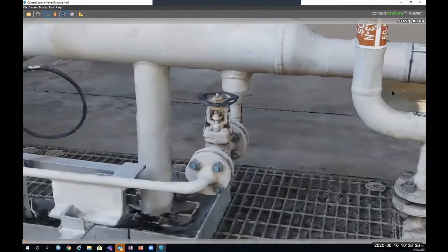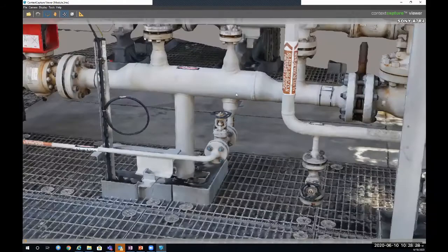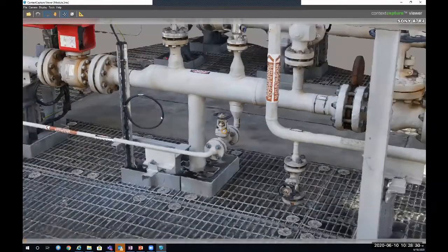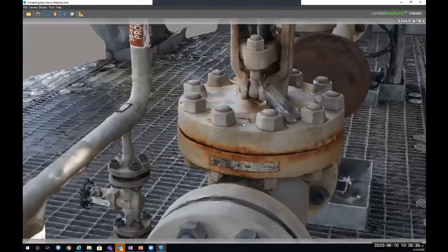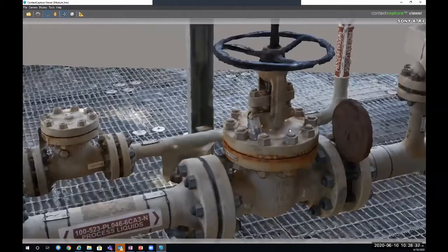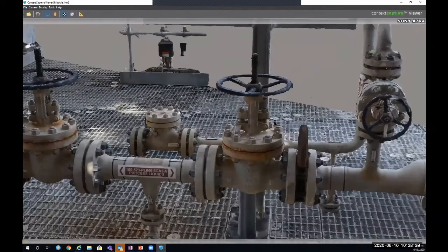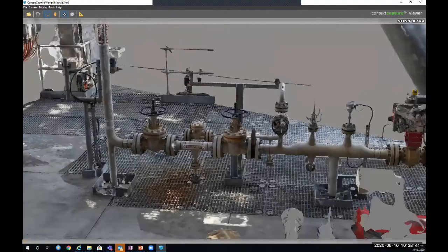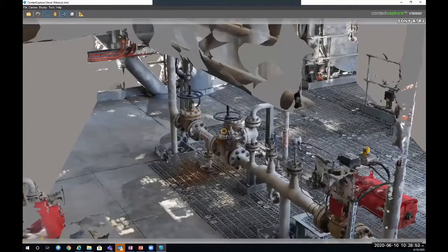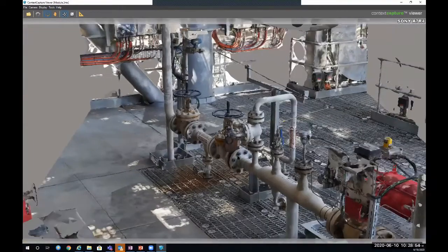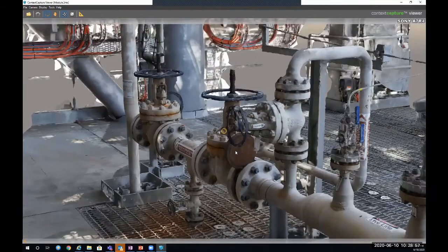What is my good data set? So this is something like this. And because you don't have any GPS on the image, it's quite important that you do, of course, a good georeferencing. So you need control points all over this area to georeference the model to these coordinates. Otherwise, this model is not even scaled; it's just captured, and that's it.